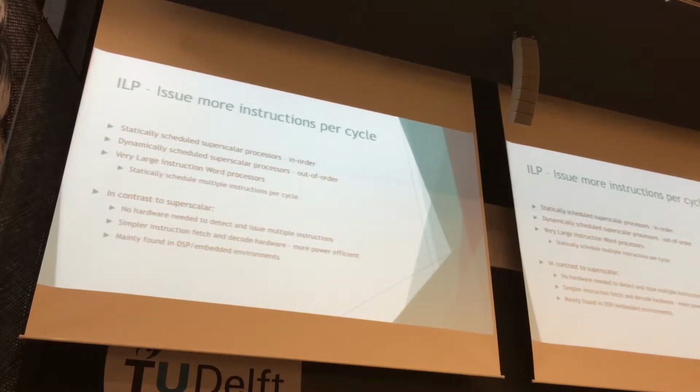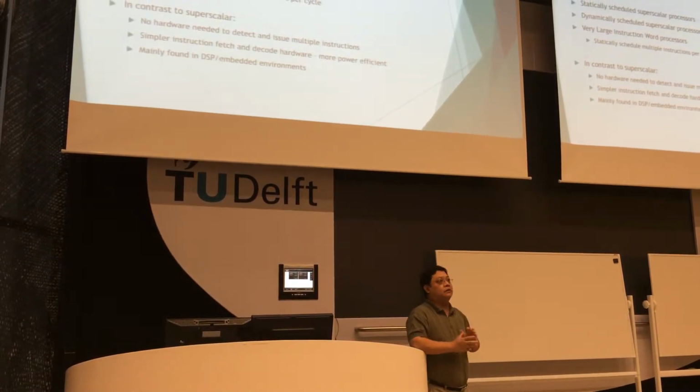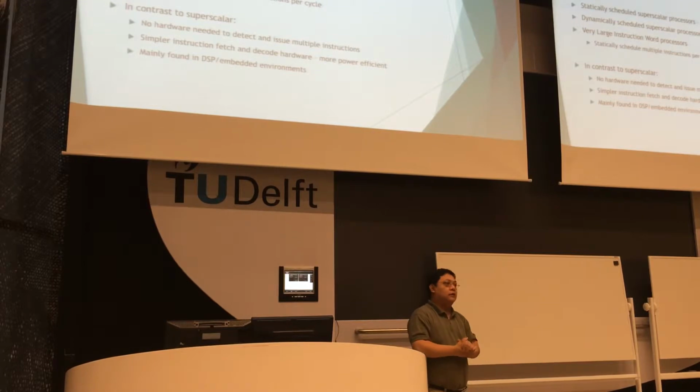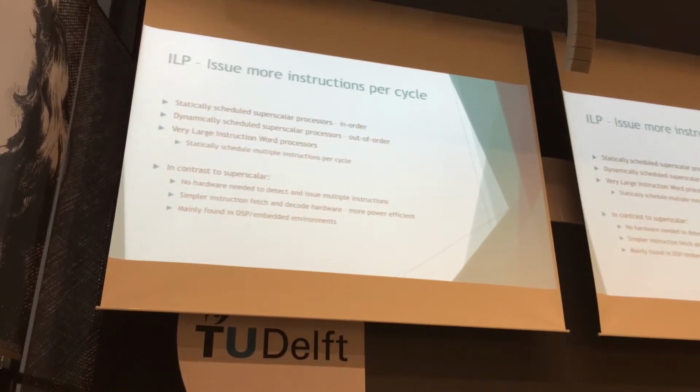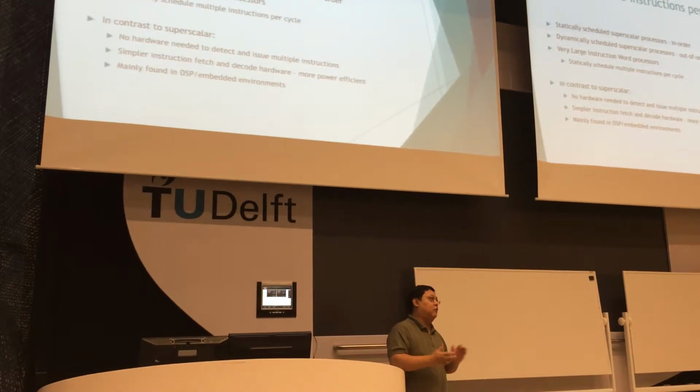The dynamically scheduled one says, well, if in this window I can rearrange the instructions in any way without changing the functionality of the program and without violating the actual program, then I can also schedule them in a more complex way in order to gain more performance, being able to execute more in parallel. But what is the big disadvantage of that? The disadvantage is that you have to have a more complex instruction fetch and decode unit with different window sizes in order to determine which instructions are really independent and which are not, and which ones you can therefore schedule in parallel.